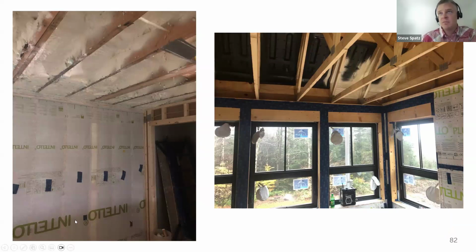Vapor control can be a combination of materials here as well too. So you have a wall assembly with dense packed cellulose behind it and a vapor control membrane over it glued at the top plate. That transitions into closed cell spray foam into a very low slope roof above. And the closed cell foam in this scenario is the vapor control layer and a vapor barrier in that scenario.